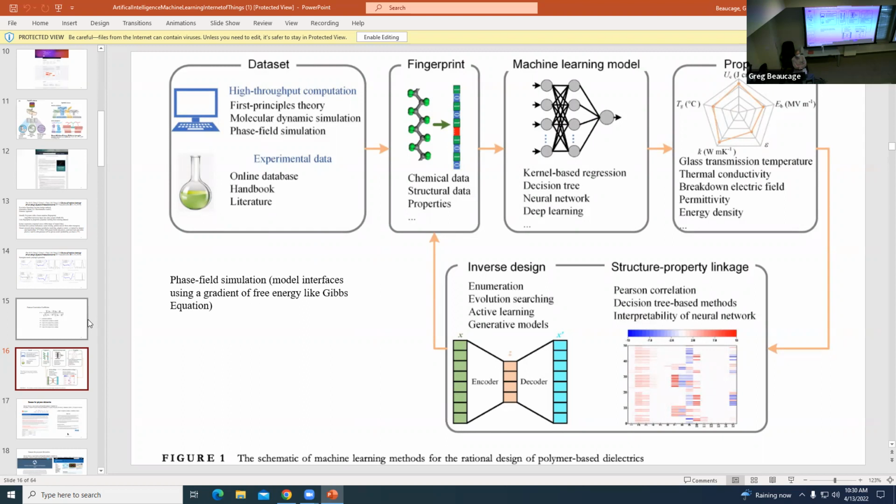So you have to have a certain spectrum for whatever application you're looking at. So the impedance matters. So basically it's going to be like an AC circuit, not a DC circuit. So you need to know the dynamic dielectric behavior, and different molecules are going to have different polarity. So when you put a field on it, the polarity of the molecule shifts, right? And that's kind of how it's storing energy. There's a relaxation time to that shifting of the polarity of the molecule, which is related to the glass transition of the polymer. So you need to know a lot of information to plan this out. And the perfect one hasn't been found.